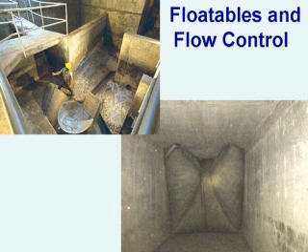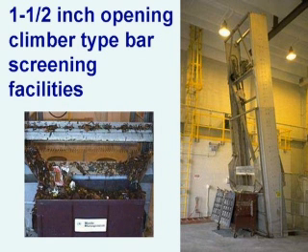I'm going to go through a series of photographs and talk about the operation. This is the upper left-hand photograph. You see this is a diversion structure. There were 16 overflows in Columbus that were reduced down to 2 treatment facilities. Most of these old outfalls have a structure like this, where the dry weather flow comes down and goes through vortex valves, and these are rather large ones, about 60-inch diameter. The dry weather flow goes through the vortex valve. When it rains, that vortex valve will start to limit the flow as the flow rate comes up and cause the water to back up.